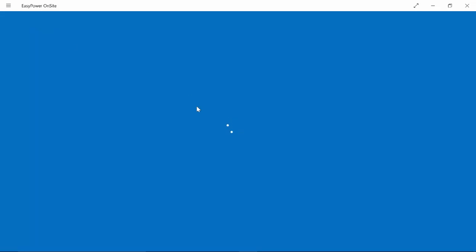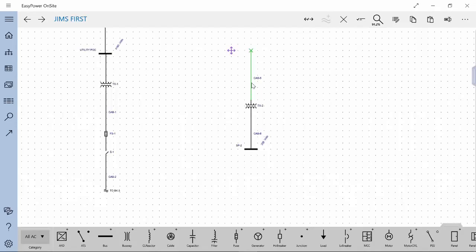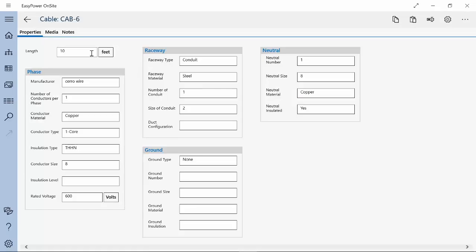Now, I see the same conductor goes from the transformer to the cable, to the lower building. So I'm going to take a copy of this conductor, copy it, and then put it down into this location. Except this one I've noted and measured, instead of being 10 feet, is actually 145 feet. So we should be good there. Okay, that brings us to the transformer.